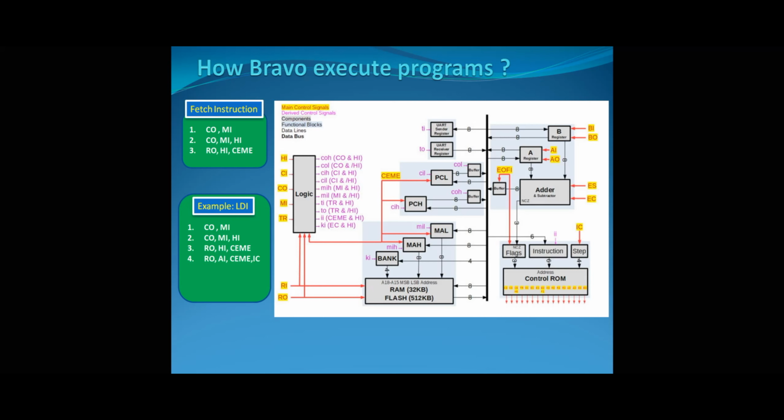To remind you of the different modules that we have built so far and how they relate to each other. If you remember, we obviously had the 8-bit bus in the middle. We had A and B registers, both 8-bit and connected to the bus. We had our ALU here, which does our addition or subtraction operation, and it has an 8-bit output again going on the bus. At the same time, we had three flags that are outputs of our ALU, as you can see: negative, carry, and zero flag. And those come into our flag register here that I just talked about.